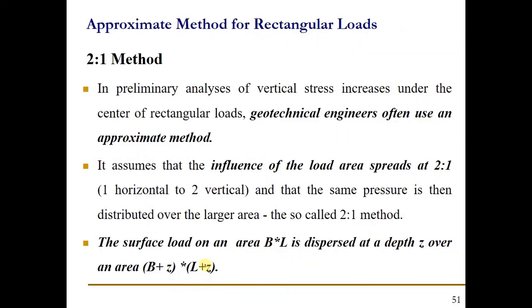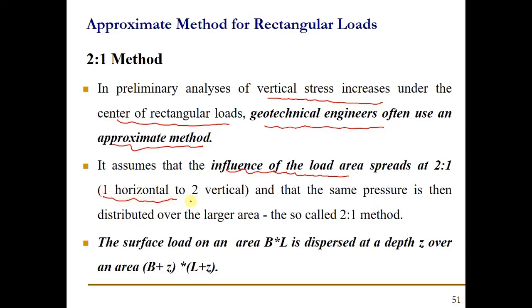We can also estimate the stress increase in the preliminary analysis of vertical stress increases under the center of the rectangular loads. The geotechnical engineers often use an approximate method. It assumes that the influence of the load area spreads at 2 to 1. That 1 is the horizontal distance, 2 is the vertical distance or the depth of that layer, and that the same pressure is then distributed over the larger area. That larger area is represented by B plus Z into L plus Z.